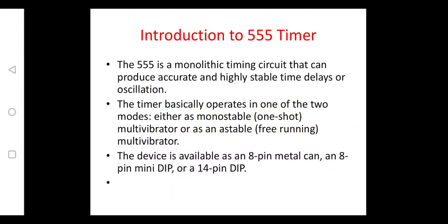This 555 timer is available in IC form with an 8-pin package or a 14-pin package. It is designed for operating temperatures ranging from -55 to +125 degrees, the supply voltage can range between 5 volts and 18 volts, and it is compatible with the TTL logic family.